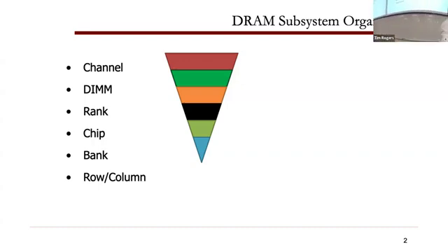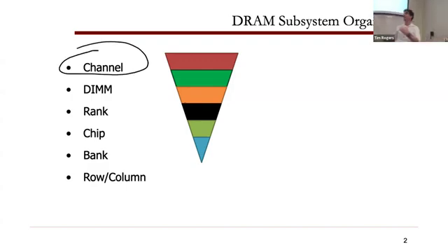Okay, so you touched on what a memory channel is. Memory channel generally means we have a memory controller on chip these days that is controlling some pins that are connected to a memory of some sort. Okay. So a channel is sort of a one-to-one mapping to a controller and pins coming off of the main chip that go to memory.